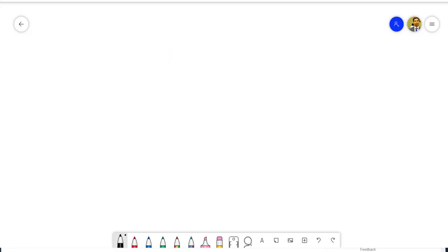So here we are taking a simple system. This is a standing cantilever, but it's not exactly a cantilever. We are just modeling a straight column whose base is pinned. This is a simple example we are creating to make you understand how the P-delta KG matrix can be formed and how it can help us in this one-step solution path.